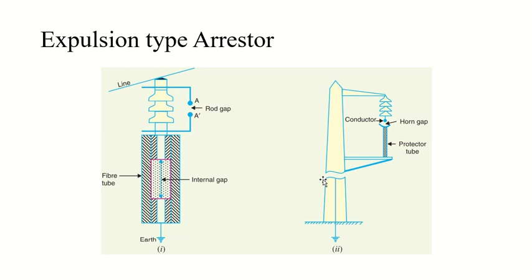Now, as the gas leaves the tube violently, it will carry away the ionized air around the arc, and this will deionize the region, right? That effect is generally so strong that the arc goes out at a current zero, and it will not be re-established at all. Now it may sound a little bit tricky, but once you read it, you will get the hold of it. Now, what are the advantages of it?